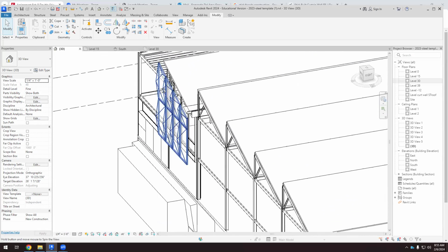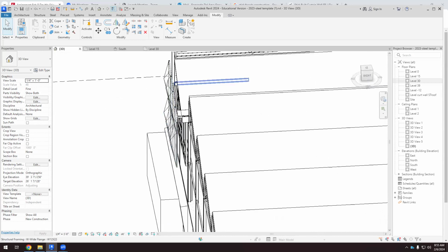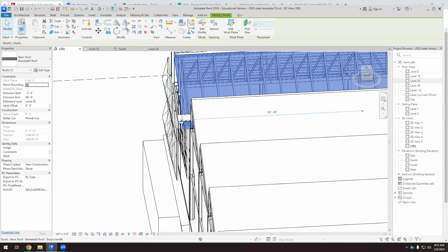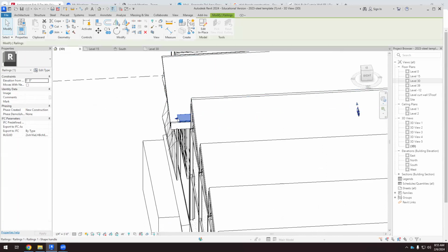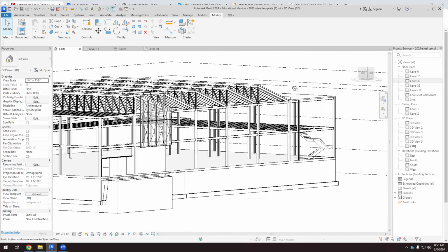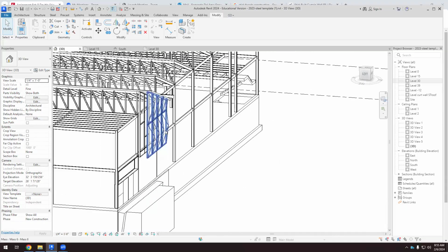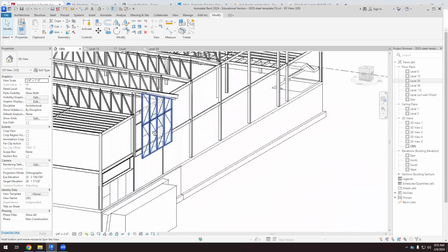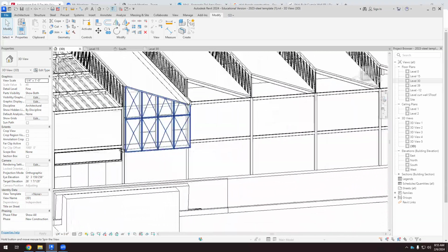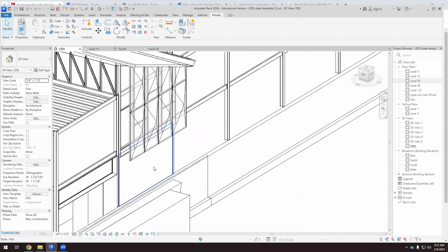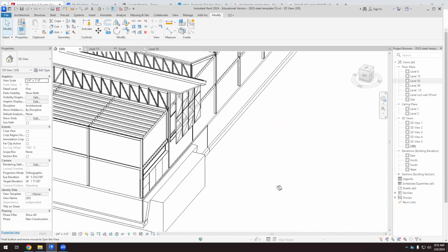Well, there's something here as well. There's a gap. We have to close this gap. So we have to extend this roof beyond the double skin, and we have to extend this gutter beyond the roof. So that works. And now it doesn't rain inside this air chamber. We don't want that. Okay. We're going to continue, and then I will show you how to create the family.